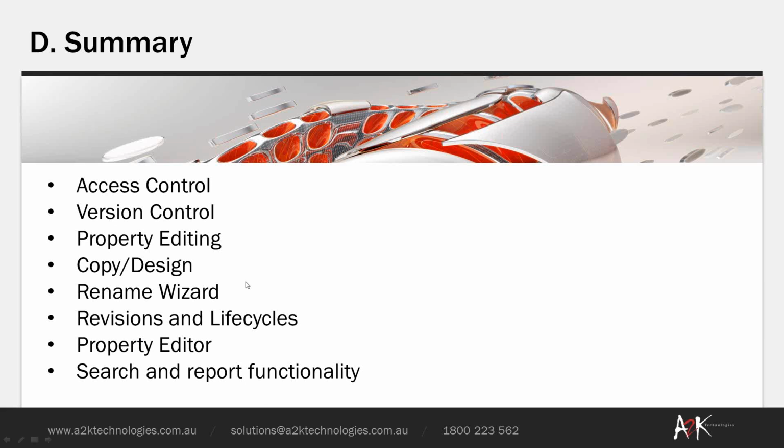So a very quick way of copying design files that contain links, renaming them, and then working on that design again completely separate from the first one. We looked at revisions, lifecycles, and the property editor. So you can edit properties really quickly and easily. And also the search and report functionality.